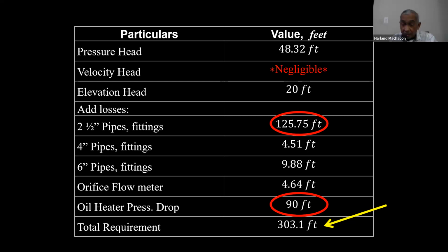Second, we cannot reduce the flow velocity of the fluid in the oil pressure because it is really designed to have a greater flow in such a small pipe so that you will have a turbulent flow, which is needed for an effective heat transfer. So this one is out of the question. You cannot do anything about it.